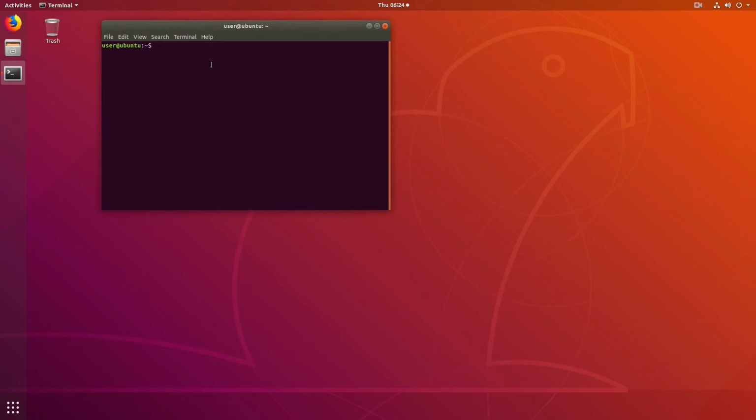As we said before, this is an example where we are going to compile an image for iCore MX8M Mini. And the Yocto version on this virtual machine for this purpose is Sumo. So we are now moving in the Yocto root directory. We can see that there is another folder that is Sumo, the name of the distribution. And finally, we are in the directory where the environment variable setting script and the Yocto sources folder are placed.